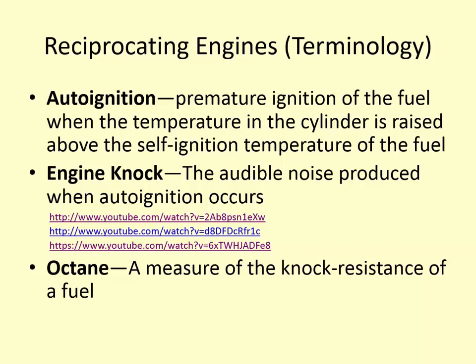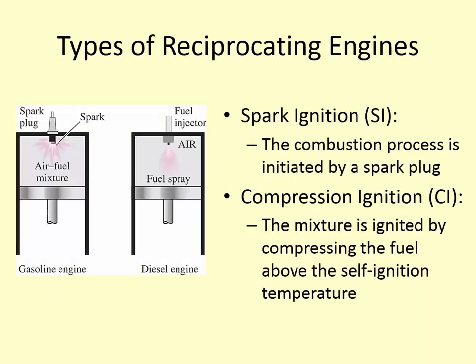Incidentally, giving a vehicle high octane fuel when it doesn't have any issues with knocking is just a waste of money because it doesn't really increase performance any. You can do that by having a higher compression ratio, but you can't change that once the vehicle's been made. So having a higher octane fuel probably isn't going to help you any if knocking isn't an issue in your vehicle, or not significantly.